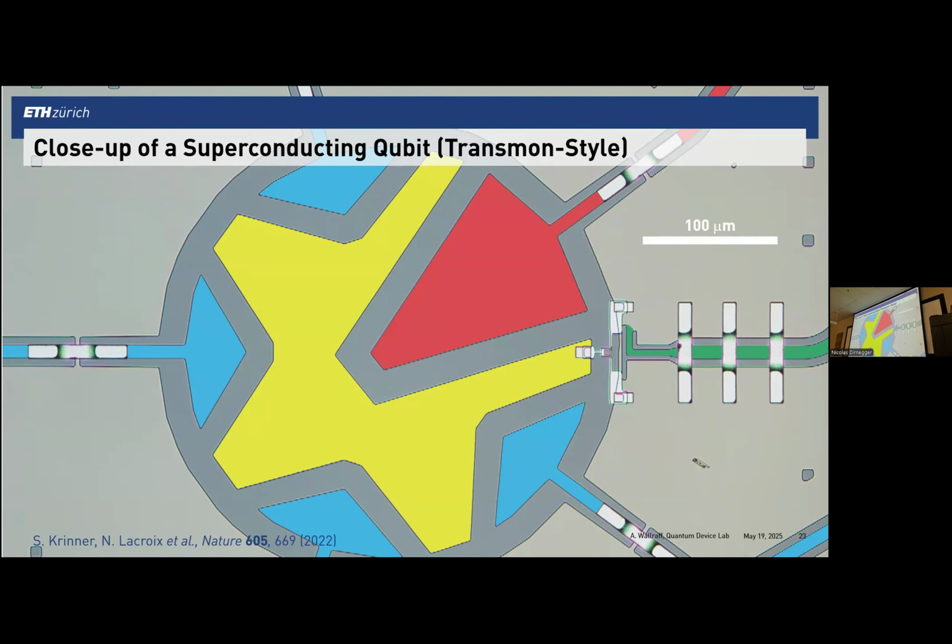Yeah, so I think the main reason why we are still sticking with niobium is if you do everything right, I think the performance is good. I think it's certainly more tricky because of the oxides and other problems. And a nice example that we make use of a lot is you can test niobium at 4.2 Kelvin, so you can do good dipstick measurements. And when we iterate designs, we tend to do that, and it's a good method for us.